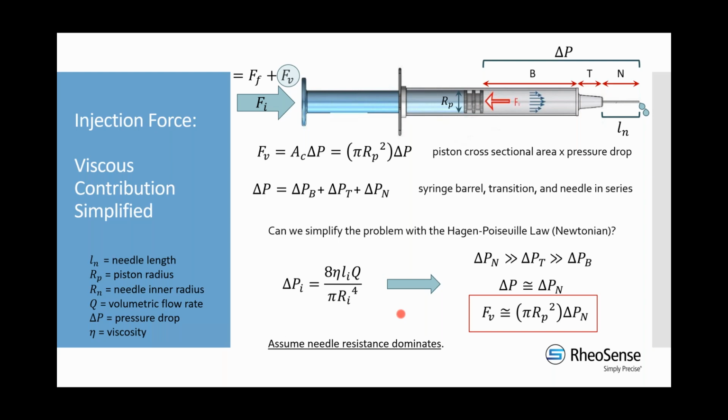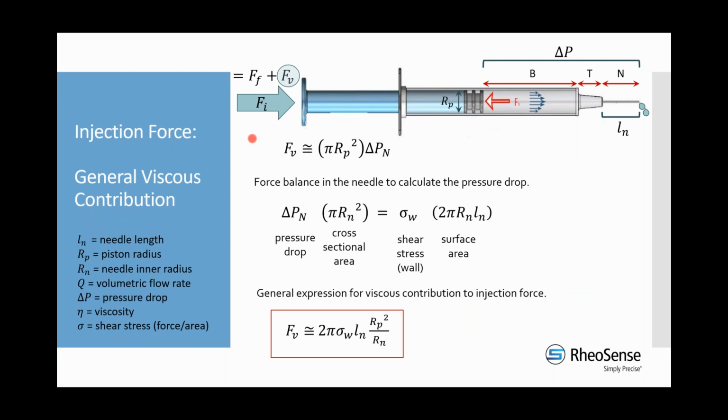So now, we know the dimensions of our syringe. Now we have to figure out how we are going to get this pressure drop that comes from forcing the fluid to flow through the syringe. So that's the next step that we're going to do. So now we're going to look at how to do this just in general. Again, we're not really assuming that the fluid has any particular properties as of now. That use of Newtonian fluid mechanics was really just to get an order of magnitude of what that pressure would be, which in this case is justified.